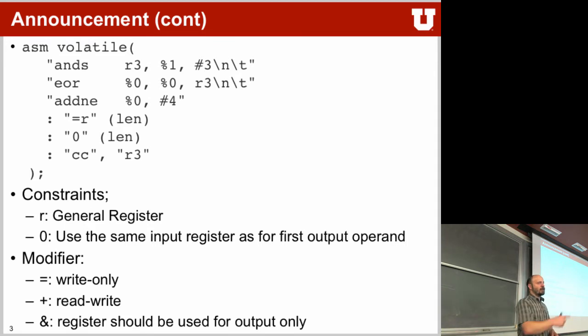Inek also made a very good point. This kind of inline assembly is used if you have assembly instructions that don't have a C equivalent. For example, on the ARM Cortex-M3, there is an instruction called wait for interrupt, WFI, in assembly. There is no real C equivalent for that, right? There is not a wait for interrupt. That doesn't exist. So oftentimes what they do is they make a hash define for WFI, and it will be interpreted as an inline assembly code line. So that's the kind of thing where you use these.